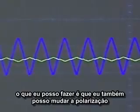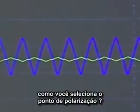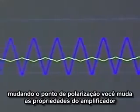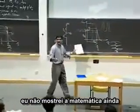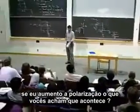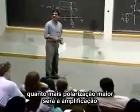What I can also do is change the bias, and we'll see this at the end of the lecture, in the last 10 minutes. How do you select a bias point? By changing your bias point, you can change the properties of an amplifier. To give you a preview of upcoming attractions, what do you think should happen if I change the bias point? I haven't shown you the math yet, so intuitively, if I increase the bias, what do you think is going to happen? Higher bias would be more amplification. Good insight. Higher bias will be more amplification.